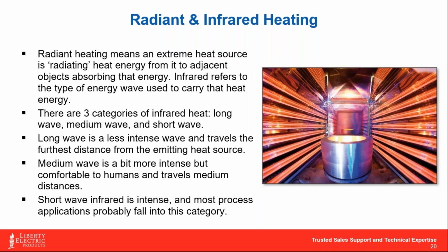Now, there's different types of wavelengths that we deal with in infrared radiant heating, and we've got shortwave, medium wave, and long wave infrareds. There are certainly layers of separation in between, but the gist of it is that shortwave heat is typically very intense. It doesn't travel nearly as far as the other two wavelengths do, but it is an intense and harsh type of heat. So you can typically heat more with less when you're talking about a shortwave infrared. It's also probably the heater of choice if there's ever a threat of cold air intrusion into the space, or if there was ever reason to do outdoor heating. That's your best bet with it.